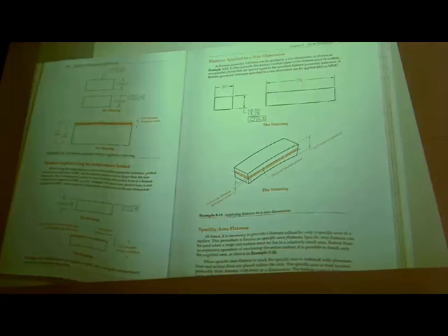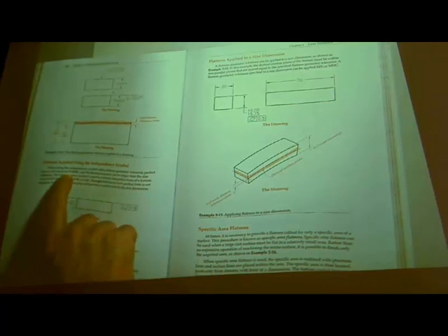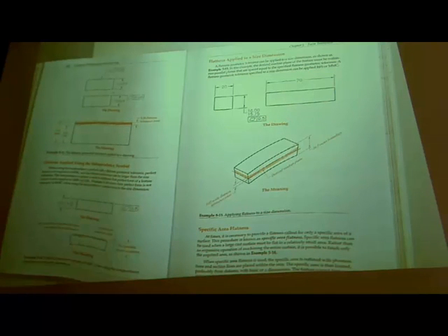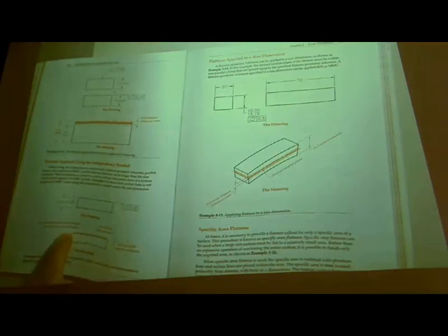And then where we want to exceed it, again, we can apply the independency symbol. We put it on the actual size, saying that this size is independent of our geometric control. So therefore, flatness can go outside of it.